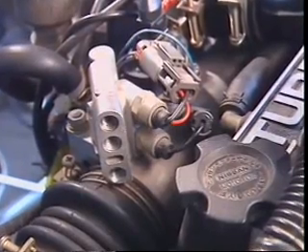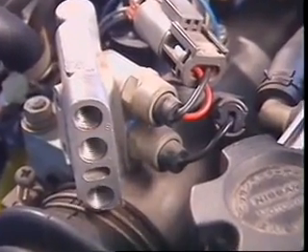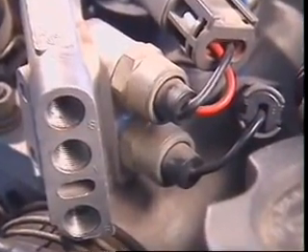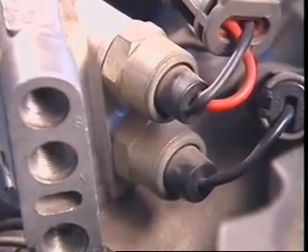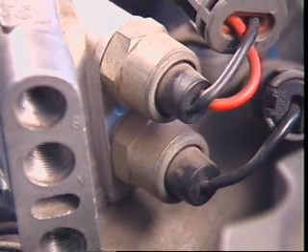Solenoid valves can also be used to bypass a predetermined amount of air around the throttle plate. These may come into operation for specific load compensation, for instance, when the air conditioning compressor is engaged. They open up a passageway of fixed dimension and do not vary the opening.